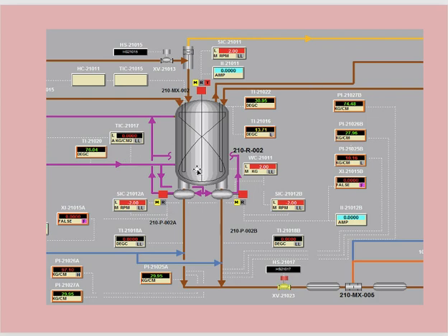Okay, here this is some kind of continuous stirred tank reactor used in the polymerization process. Okay, many parameters we control through this reactor. You will find the pressure. This polymerization process works under a vacuum, so there is evaporative cooling achieved by this equipment additional to the reactor, by evaporating and making cooling and making a return reflux to the reactor.